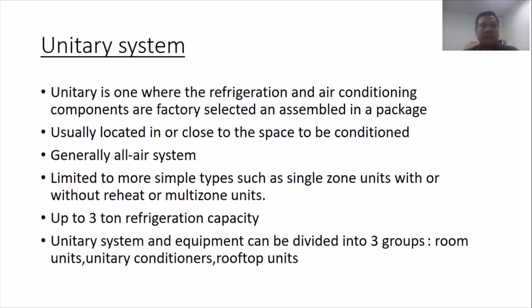This is different from the multiple system, where we have to construct a duct system, construct the equipment, distribute to every zone, condition, and then control certain zones and certain conditions. Okay, and then usually it is located in or close to the space to be conditioned. So actually, a unitary system is implemented close to the conditioned space. So not too high, very close.